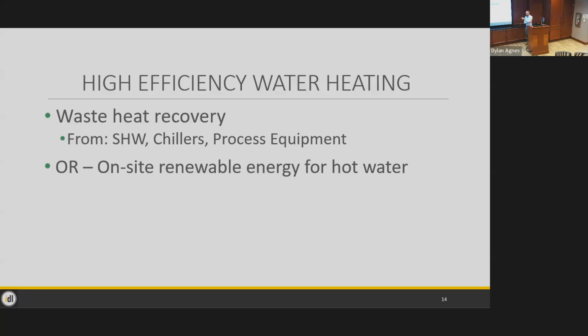The book that I've been using by Allison Bales, "The House Needs to Breathe," has one of its final chapters on water heating, so my class had to go through that Friday. And he argues that solar water heating is dead. At least it was in 2014, and now running the numbers again, it's really, really dead. Because of the cost of plumbing solar hot water, and you still have a backup system that's required for cloudy days and things like that, it adds up so much that the infrastructure tends not to pay itself back.